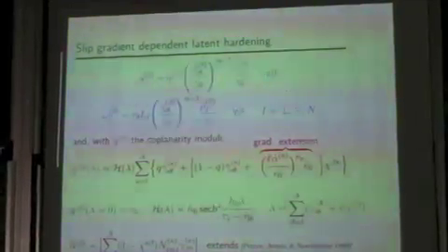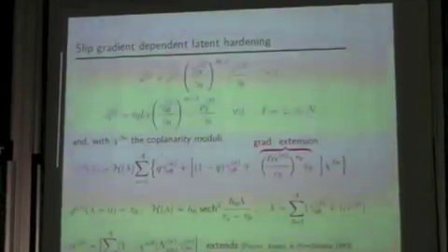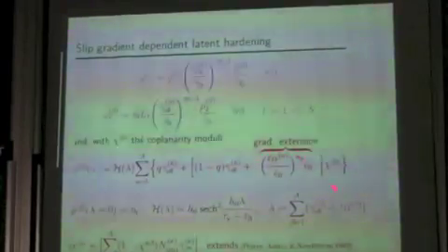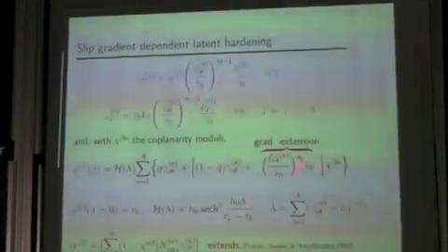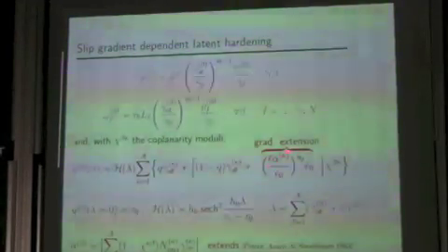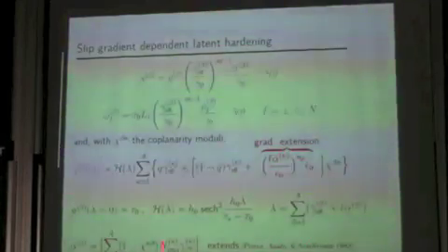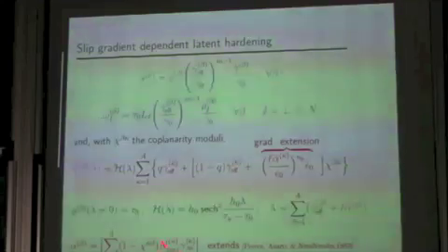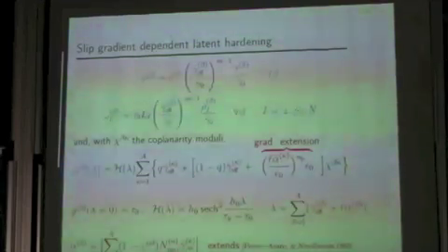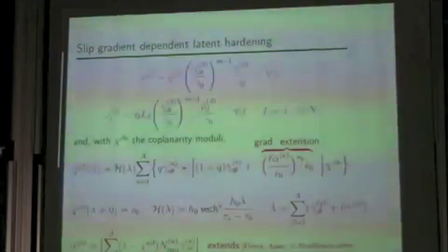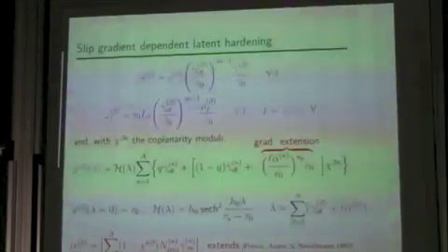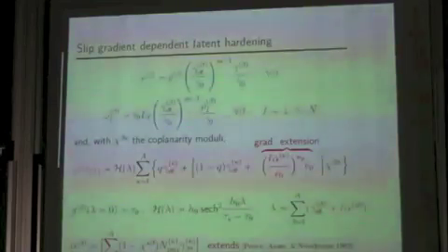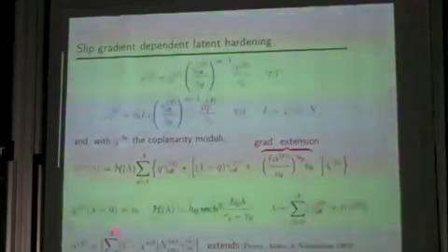But then, in order to try to model somehow what we observed with dislocation dynamics, we had to put also this extra term in which this scalar dot alpha, let me just say, because it's quite complicated, accounts for the increment in dislocation densities on different systems with respect to the one you are writing the higher order balance equation on.